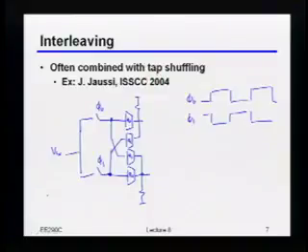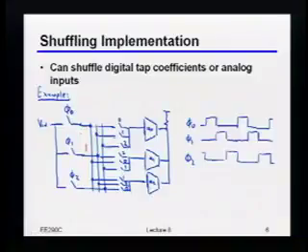And by the way, you can see I complained a lot about it, but for 2 taps, maybe even 3 or 4 taps, it's complicated, but it's not that bad. It's really only if you start talking about very complicated things, maybe 5, 10, 20 taps, that it starts getting painful because the noise starts to accumulate. So, as I said, it's not particularly popular in high-speed links simply because in links, many times, if not directly, maybe indirectly, you can go back to your transmitter and say, okay, you should be doing the following FIR filter to operate on this particular channel.